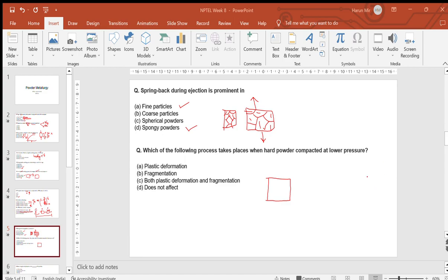So we are just changing the mold type from a cylinder to a rectangle, considering the viscosity of the mix as the same. We are trying to have a mixture of powder and binder which is the same whether you are using a cylindrical mold or a rectangular mold. So this parameter eta is the same for both. We are applying a pressure of 20 MPa, that is also the same. So you just have to compare the mass flow rates based on their dimensions, because that is the only parameter that is now changing.